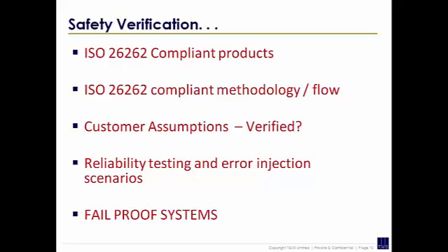So here, when I'm talking about error injection scenarios, we have many categories. We have something called targeted error injection. Targeted error injection means, let us say there is a flop. What happens if the output of that flop is changed, or it is getting negated or something like that? It's targeted, meaning it is like a corner case. This is one place which is crucial, and you inject specifically there.